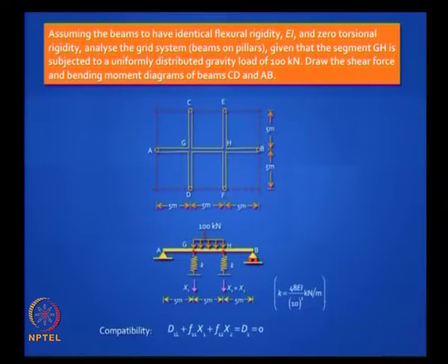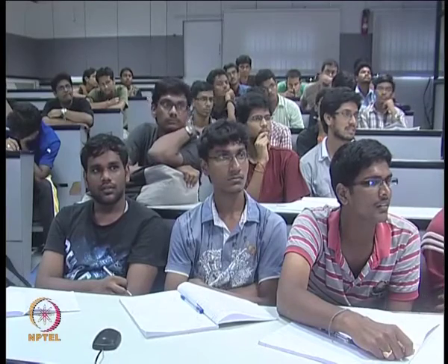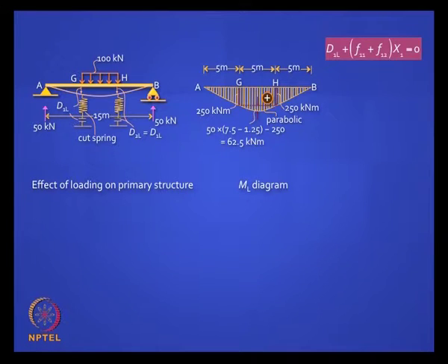You can work out all those quantities, and taking note of the fact that x1 is equal to x2, it reduces to that equation. So I will quickly show you how you can do that. You need to now find out d1L, F11 and F12, right. So your first thing is you need the bending moment diagram when x1 and x2 are 0 in the primary structure. That is easy to do, okay. You have a UDL, so you have a parabola in the middle and you have two straight lines, and those areas are easy to compute.